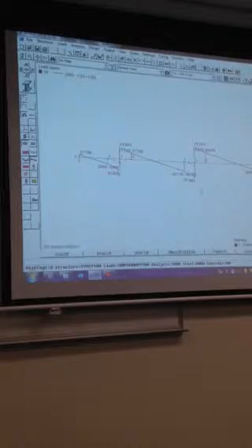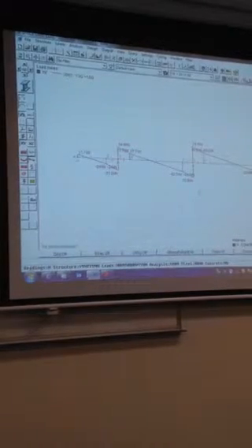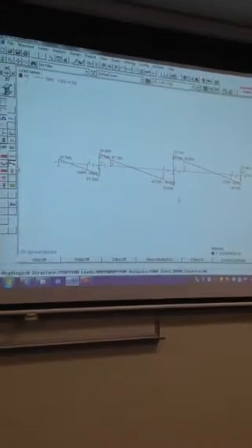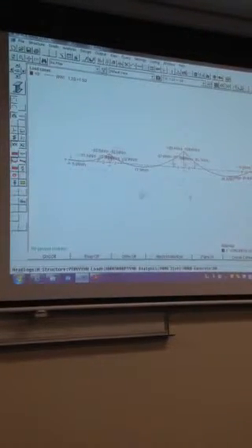So if we look at that distribution of shear force, it looks pretty good. That's what I'd expect. There's nothing funny about that. And the bending moment diagram through here as well. So the advantage of putting those extra nodes in at these locations here is when we're designing the slab, we actually need to design for negative bending moment. So negative bending moment is the top or the bottom in tension.